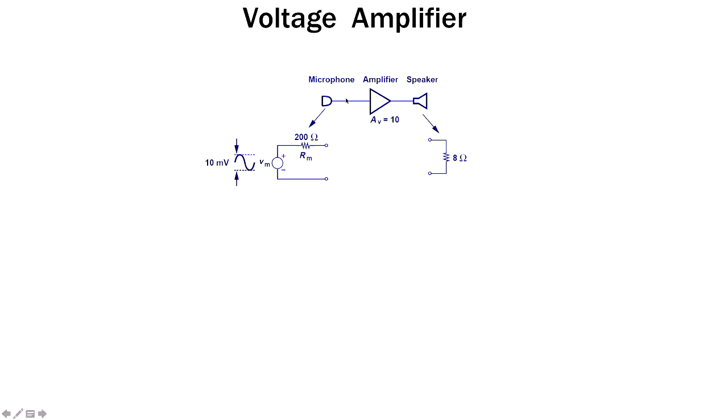Without connecting to the microphone, you can measure the voltage of this microphone output, and you found maybe 1 microvolt, and you need maybe 10 microvolts. Then you design a voltage amplifier with gain 10, and you say, okay, we got the gain of 10. But the problem is that when you connect it here, you don't get this gain of 10.